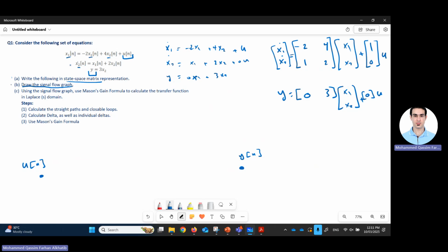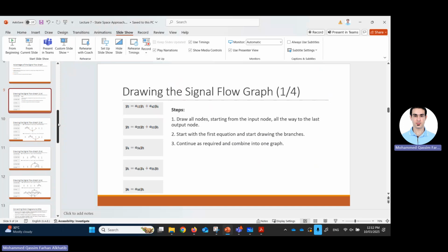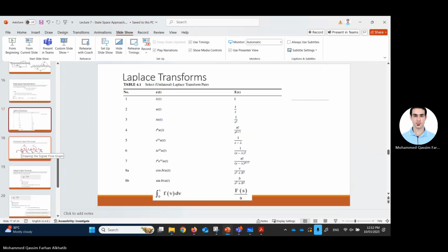How to go from a derivative to the actual function? Let's say I have my input x1 prime and I want a certain unknown block to give me x1. What will this block be? Integration. Now, what is the process in the Laplace domain that will grant me integration? Integration in the time domain is represented by multiplying by 1 over s. So if I have my input x1 prime and I want to add a certain block to get x1, I will use 1 over s.